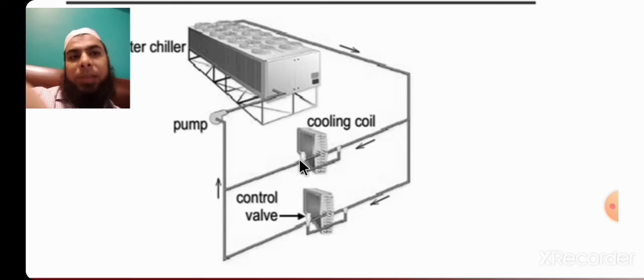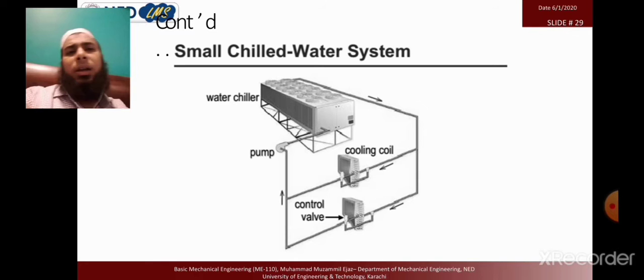So we have a bypass line by which, if we shut this valve, the water will not come to the cooling coil, but bypasses and goes like this, and circulates this way, then is cooled down by the evaporator of the refrigeration heat exchanger. If one room has reached the set point, this valve shuts off, while the other does not, so it continuously runs through the control valve. In this way the controlling circuit also runs.